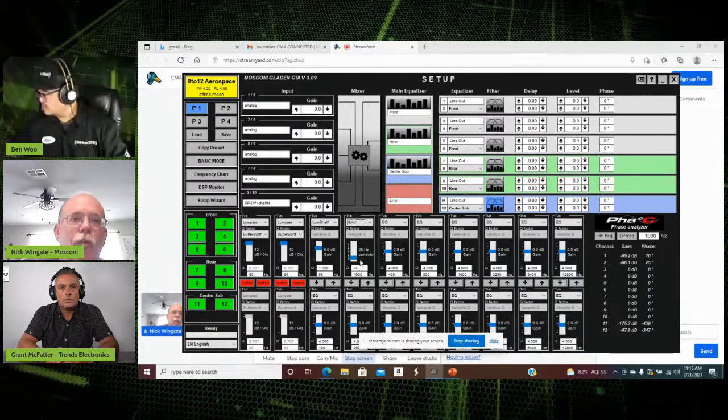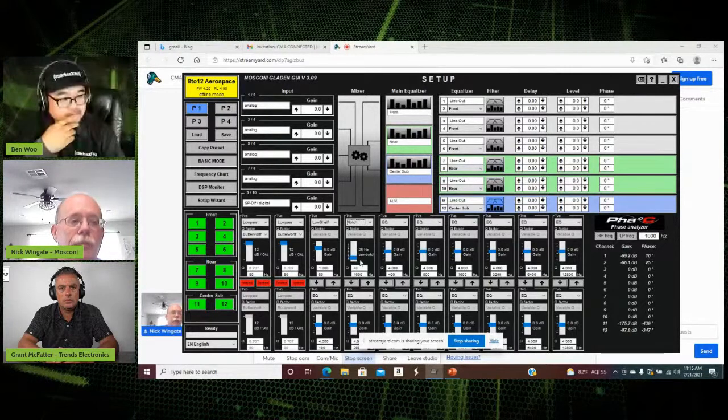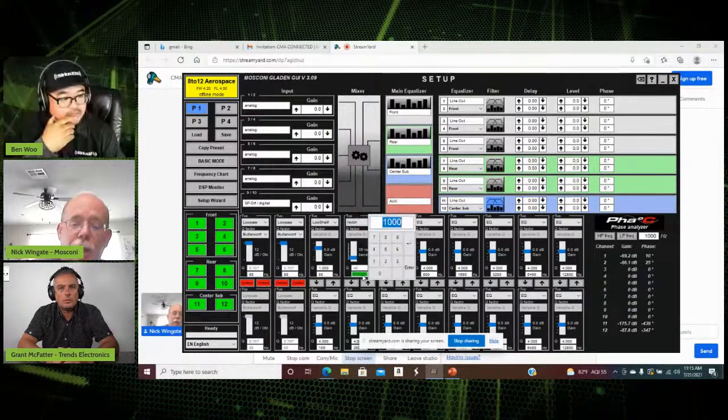Okay. So, for instance, let's just say we run a sine sweep on a mid-bass driver in the door. We've done everything we can to damp the door correctly, but we still have something going on. A lot of times I find that to be around the 180 to 200 hertz range. And you can't get rid of it. It's there. We've got this really nasty 10 dB peak at, let's say, 180 hertz. So what you do is you go to your notch filter and you type in 180 hertz because you ran your tone generator and found the exact frequency.